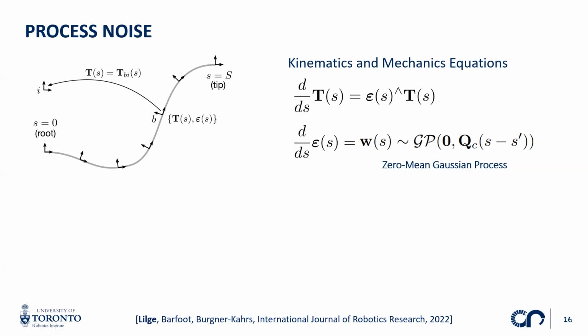They're very heavily penalized in my prior cost terms, because a continuum robot doesn't really shear and elongate, but it can bend and translate. Tuning these cost terms tells me how smooth the resulting shape will be, and I can make sure that I have a smooth center line. Then I only need to consider the measurement compared to a specific discrete node. I hope that made sense.